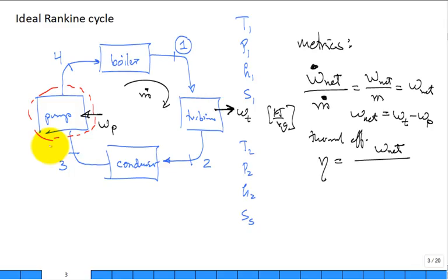It's into the pump, and now I'm going to always talk about a positive work into the pump. So when I calculate the work net of the cycle, what do I have to put right there? A negative sign. As an engineer, I take responsibility for my negative sign. And so yes, there's a deviation from the standard traditional form of the first law for a generic control volume, and we put a negative sign in front of a positive work of the pump.